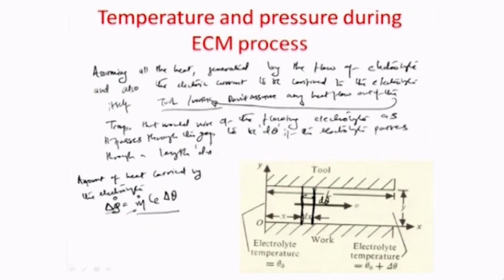So, in this particular case, if we assume that the electrode is of a depth within the plane of the paper L, and a total height y as given here, which is also the equilibrium gap, and we assume that the heat is flowing perpendicular to this shaded face.